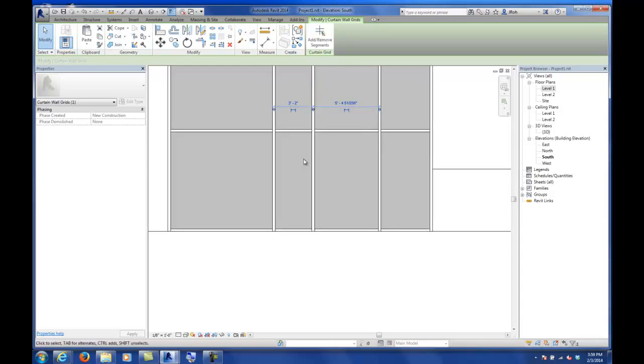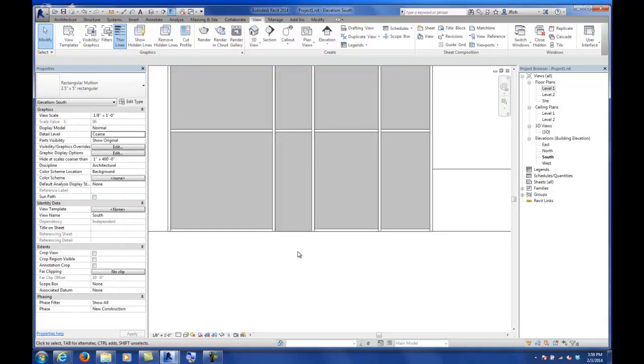It's a 3 foot by 8 foot door that I'm going to put in there. I'm sizing this to be 3'2" by 8 foot 1, and that's because I'm also going to delete out this bottom mullion. So if I click on that mullion and hit delete, I've now framed where this glass assembly is that I'm going to eventually turn into a door.